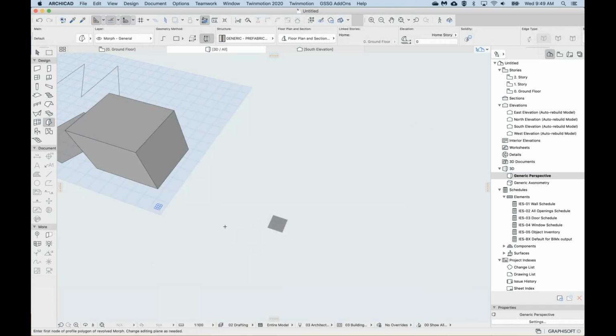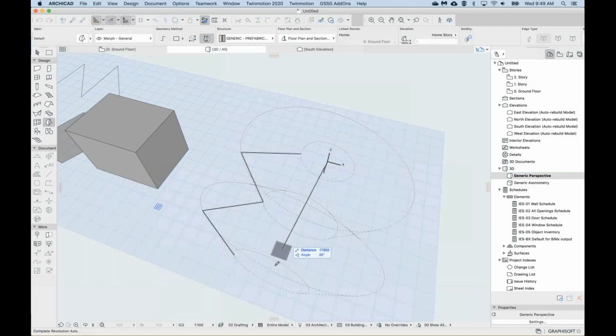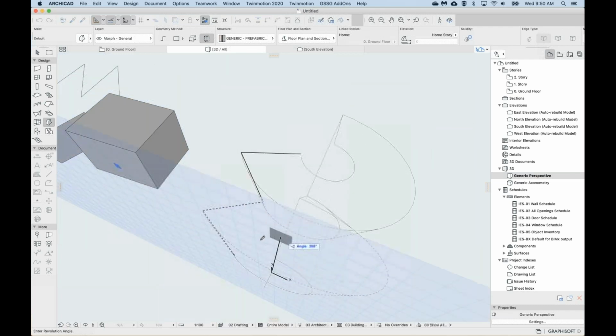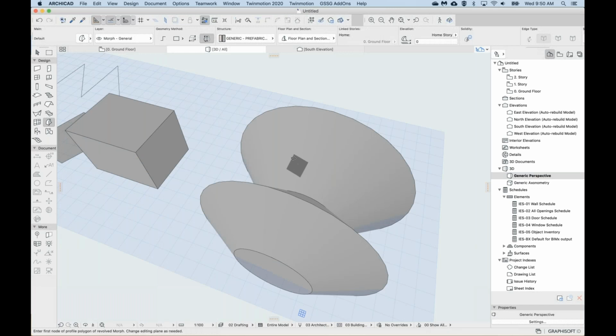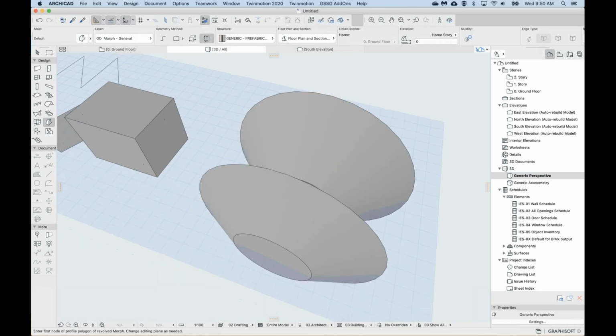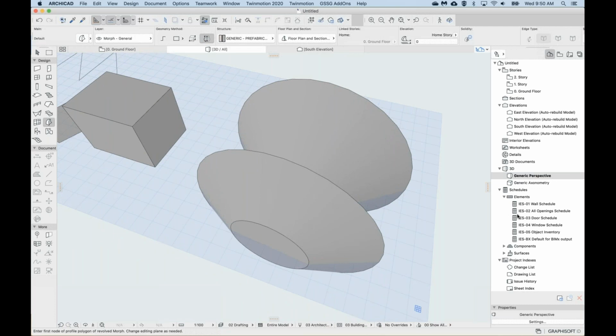So I'm going to delete mine and do it once more. I'm going to draw an M, finish the polyline with a second click or right click and OK. Then 2 clicks to indicate its axis, where it's going to rotate around. And then a revolution, so how far it goes around that axis. So it's a lot more clicks than say the box. Okay, Jessica, I think she has it.